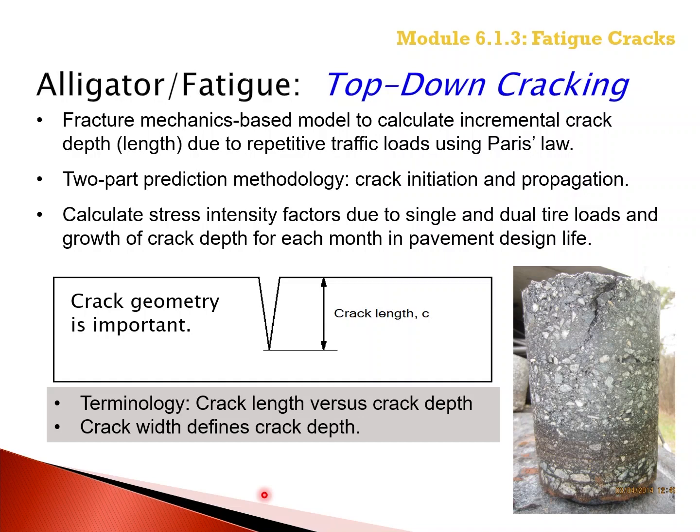However, the term crack depth is applied to the downward growth of top-down cracking. So crack length and crack depth can mean the same thing in PMED design software. However, crack depth is the specific term used for determining how fast or slow the crack initiated at the surface propagates downward through the asphalt layer.